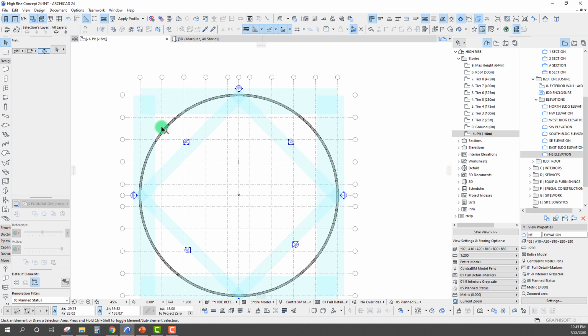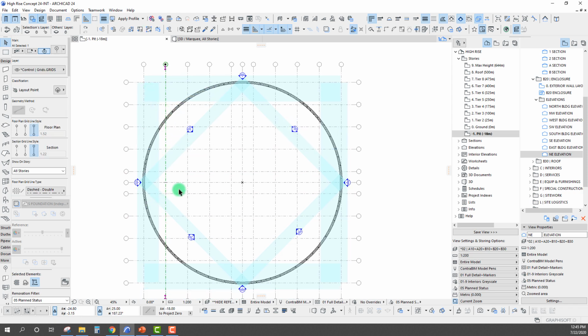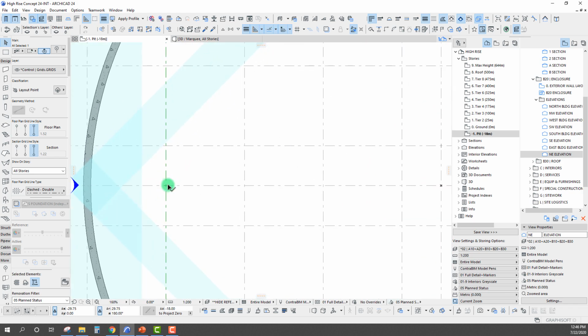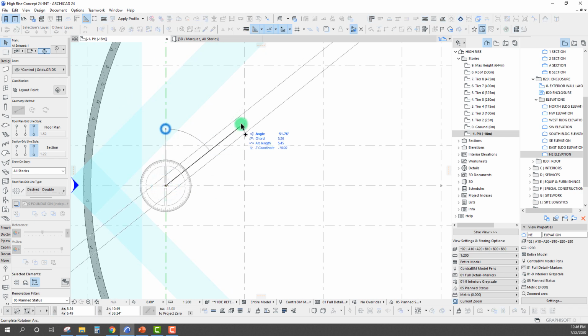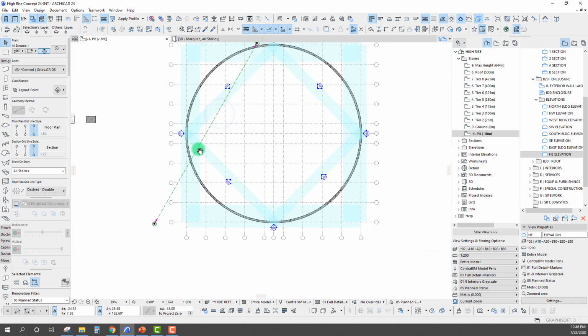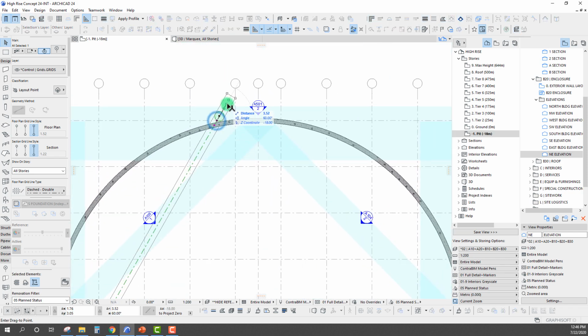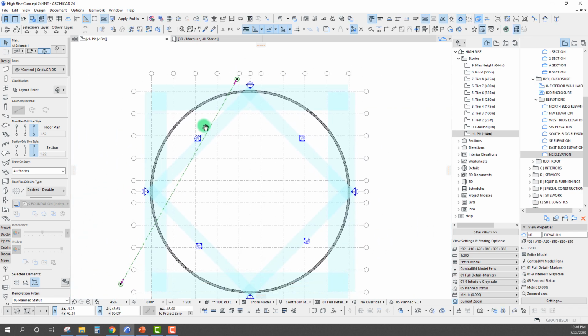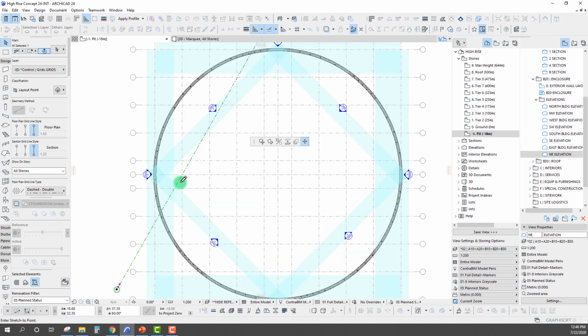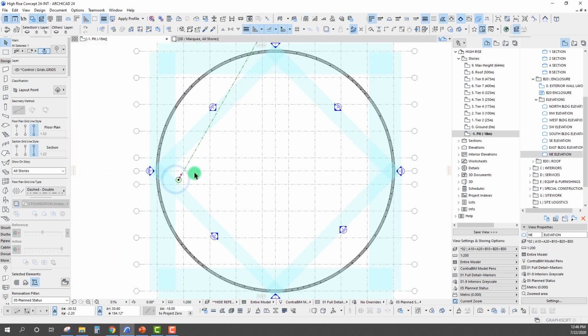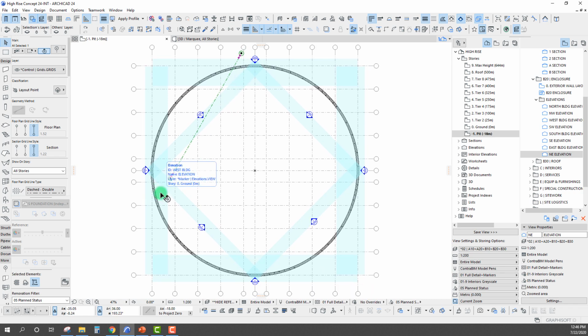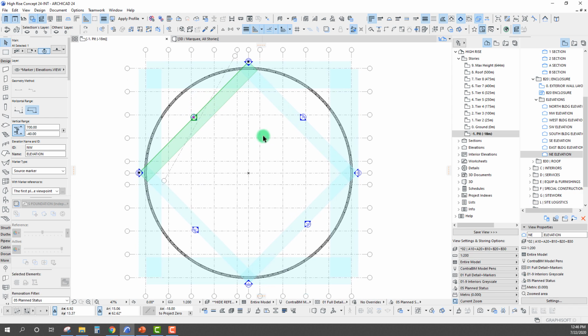So we have a working point here that's going to be from this location right here. I'm going to rotate this particular grid, and we're going 30 degrees here. I'm going to shift it on up so that we're pretty close right here. We can always offset those. And I'm going to pull this in just a little bit. Okay, so that's going to be one of our lines. We'll adjust these different elevation markers in a few minutes. So that's one of our controls on the project.